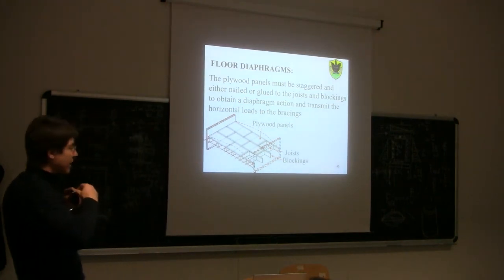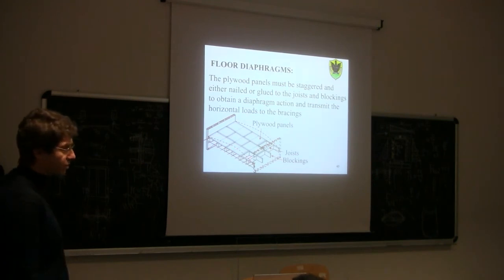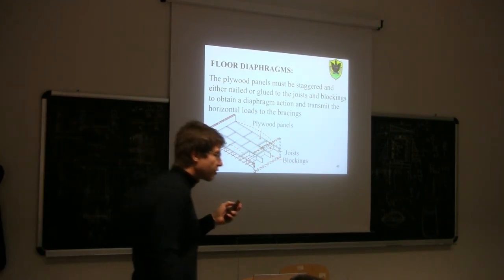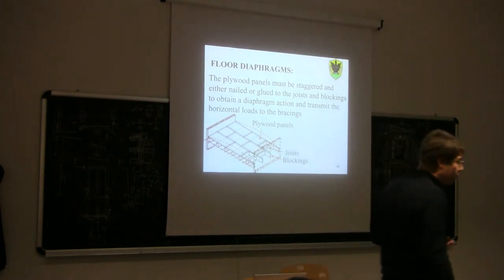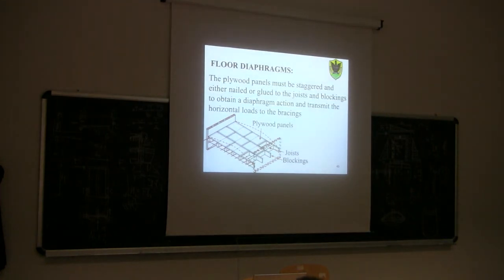Now, talking about instead the in-plane action. Now we're going to talk about the in-plane action. So those horizontal forces, what kind of stresses are they going to induce in those members here? Can you try to see? So this one works like a simply supported beam lying down horizontally, subjected to a uniform distributed load.